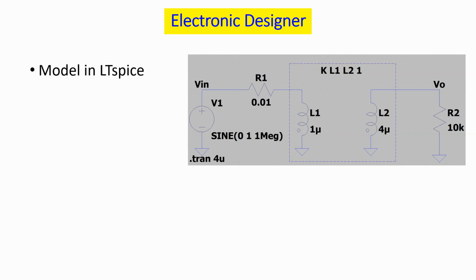So this is the first thing that we're going to look at, and another thing that we're going to see is how the ratio between V out and V in is formulated in this simulation to get some intuition. This is the ratio between V out and V in, the square root of L2 divided by L1. Okay, and we will also see how, if we change the frequency of this sine wave as an input, we can get the required output with the appropriate inductance L.